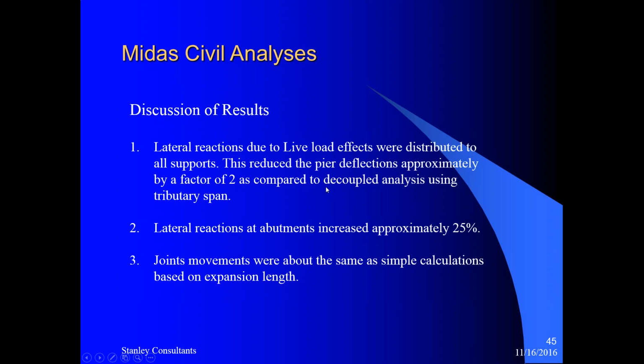A lot of the loads propagate to the more stiff abutments, and because of that reason, the lateral reactions at the abutments increase approximately 25%. However, the joint movements were about the same as simple calculations based on expansion length.